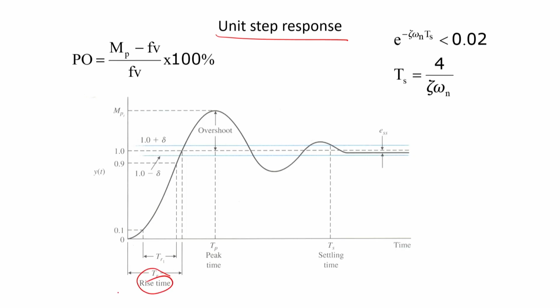That means, if unit step is my desired reference, then the time required to first reach your signal to this point, is called the rise time. Some people define it against the time between 10% to 90%, particularly in Japan, but we will keep our definition as the first time you are crossing this point is this cutting with the desired level.